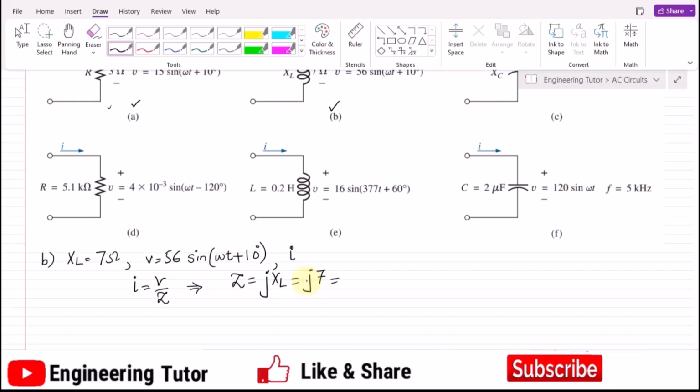We have previously discussed that whenever you have this j, it will be 0 plus j7. This is the rectangular form, and in polar form 7 will be the magnitude and the angle associated with it will be 90 degrees. Okay, so that will be in ohm. That is for the impedance Z.